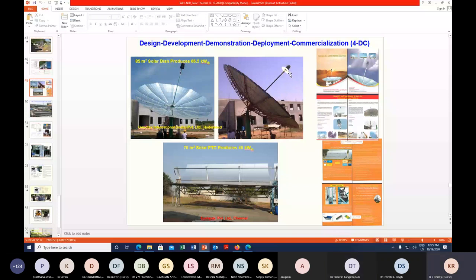So how do we reduce the area? You make a smaller receiver, so that you will have a better efficiency. And how do you maintain a smaller receiver? You make an accurate parabola and a very sharp focus. The heat loss coefficient is mainly due to convection by air, convection by wind and other things. So you try to avoid the wind by having another envelope over that.